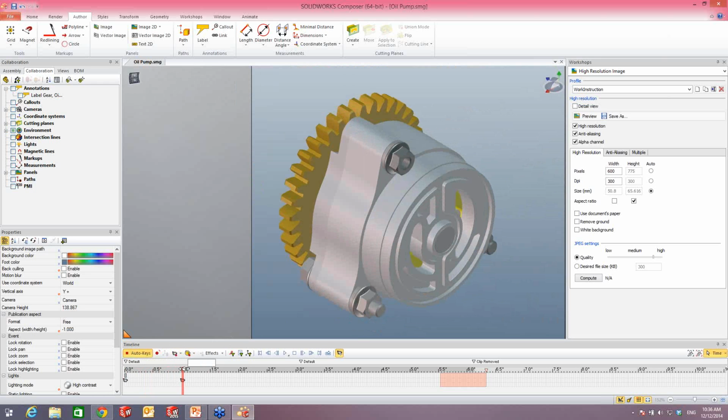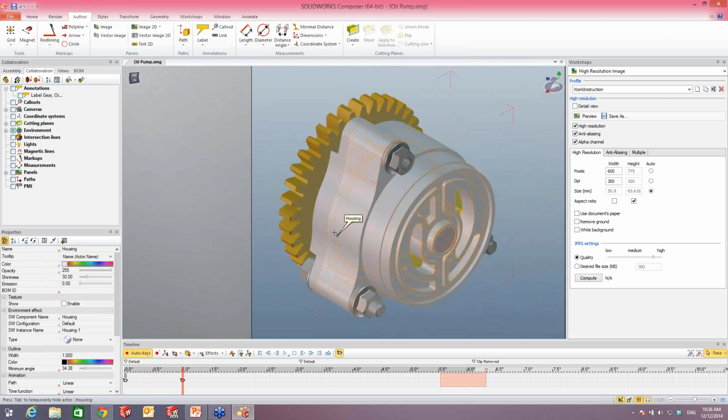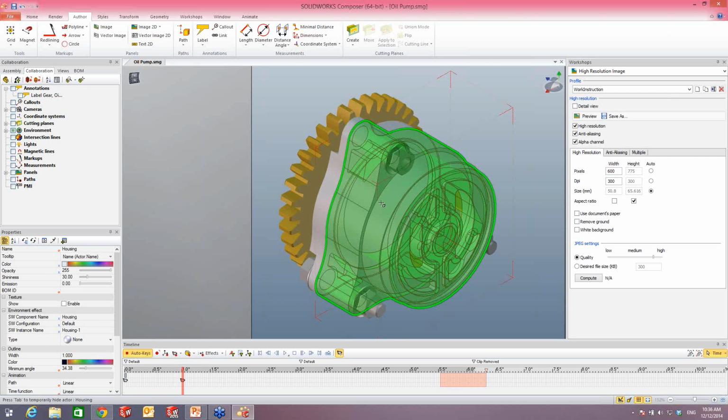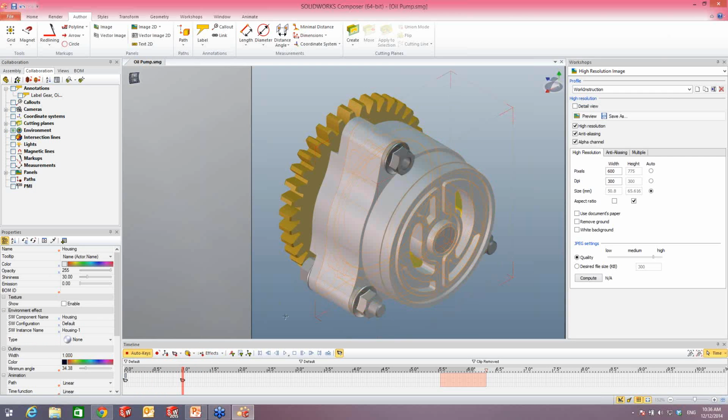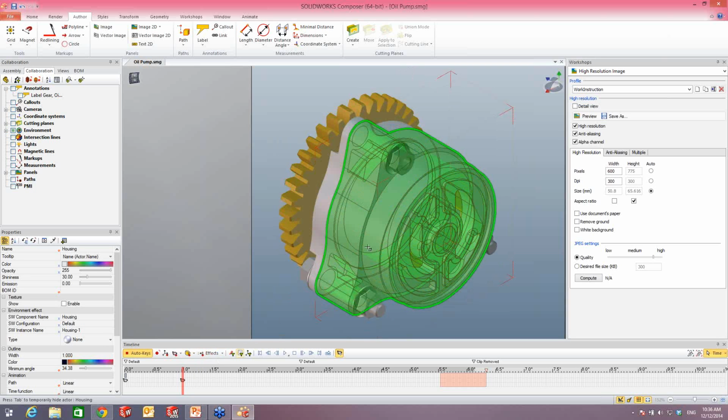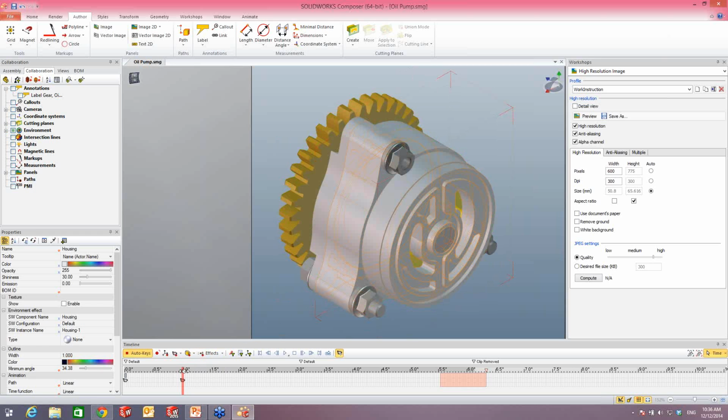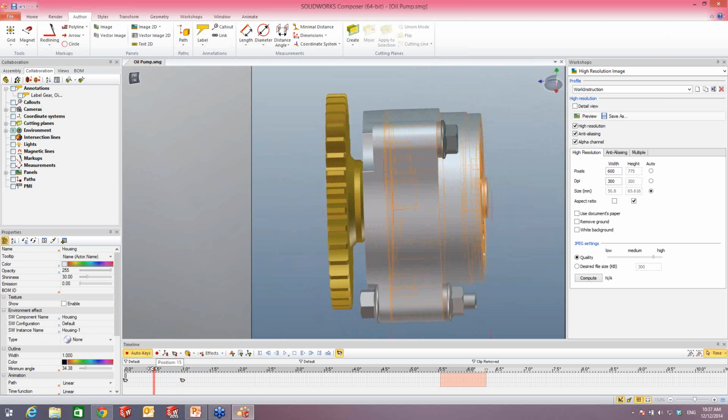If I could just mention, oftentimes what we talk about in class is people forget to do one important step. When you're doing the keyframe animations, you want to capture the actor's current settings. So say for this cover, if I were to want to make that transparent at this point in time, I might not want to set it transparent now, because it'll essentially be going transparent from 0 to 1 second. But perhaps I go back to about a half a second, and then I would capture its settings, quote unquote, by using the capture key or set key.